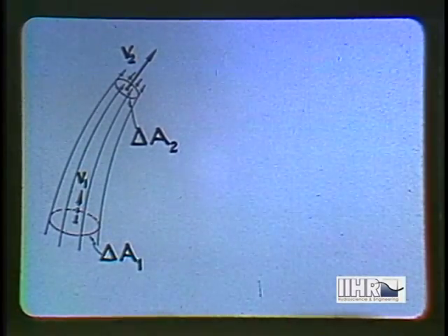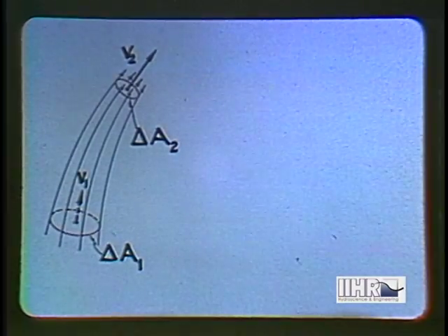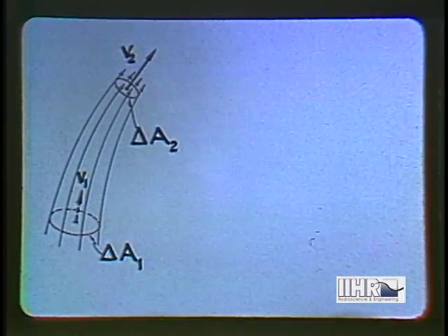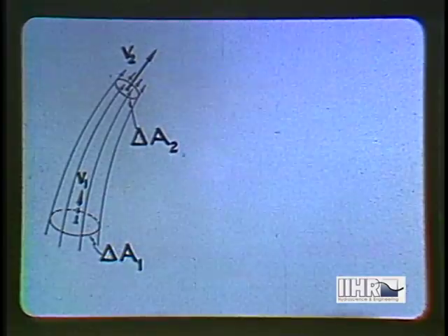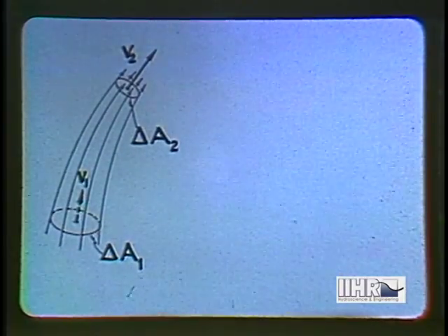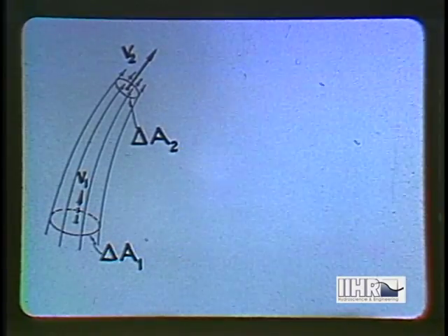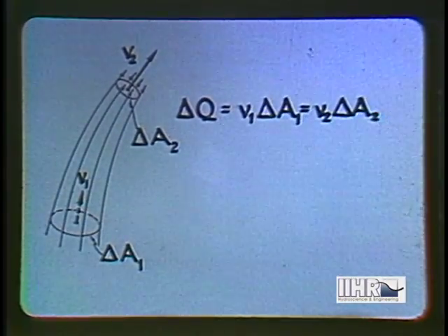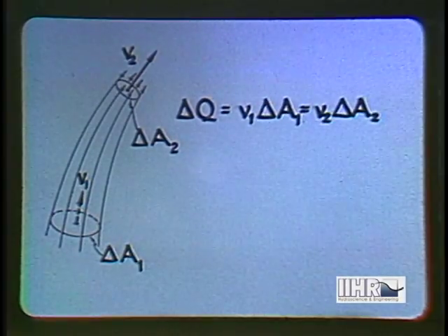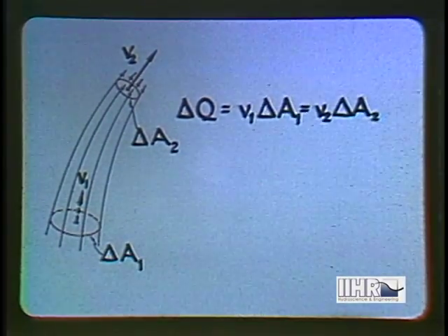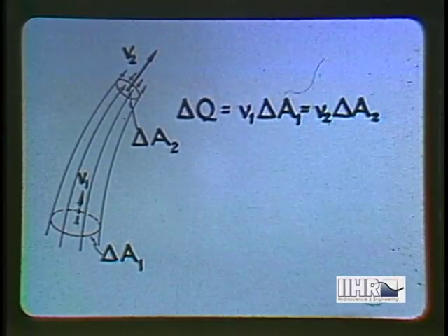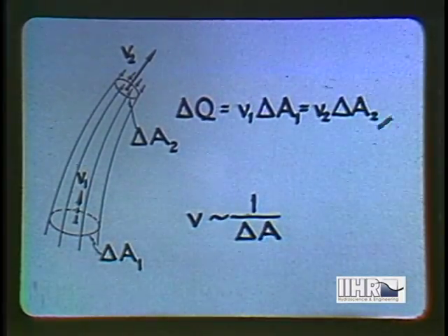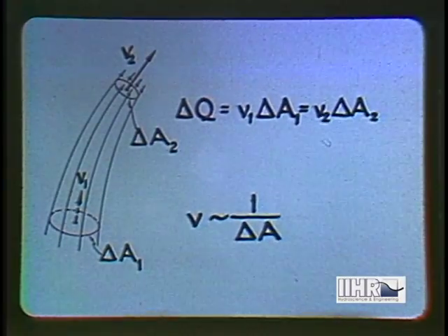The passage formed by a closed surface controlled in shape by a group of streamlines is known as a stream tube, and the fluid contained within it is called a stream filament. By definition of a streamline, there can be no flow through the walls of a stream tube. Hence, unless the fluid expands or is compressed during motion, at any instant the rate of flow past successive sections of the tube must be the same in accordance with the principle of continuity.